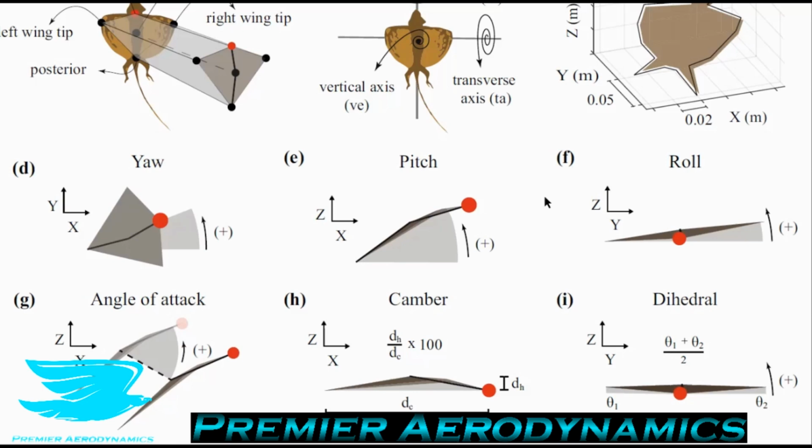The alternative is called anhedral. That's where you flex the wings down, and this has the exact opposite effect. Most aircraft do not have anhedral. There are a few. They're mainly transport aircraft. For example, the Antonovs, which are Russian transport planes. They typically have anhedral, but that's not due to stability reasons. That's due to getting the wings off the ground. So when you're loading stuff in and out of the cargo plane, you can get your trucks and that around easier. You don't worry about bashing into the wings. So that's practical concerns there.